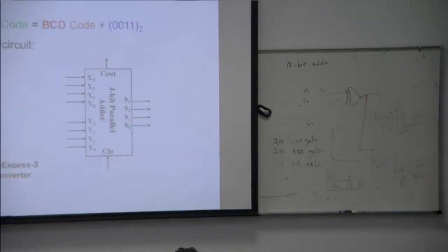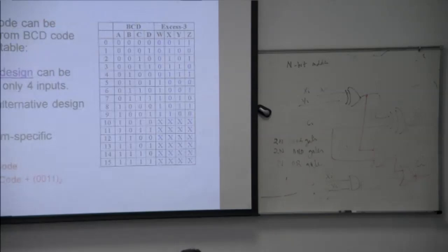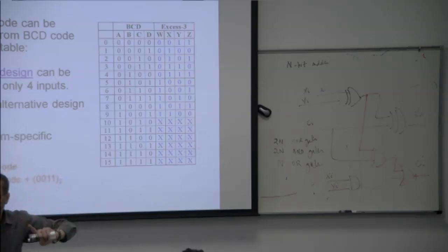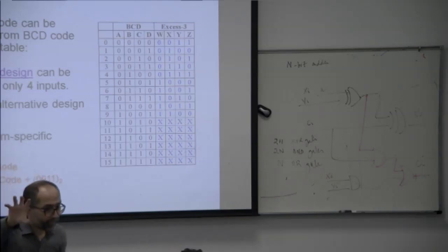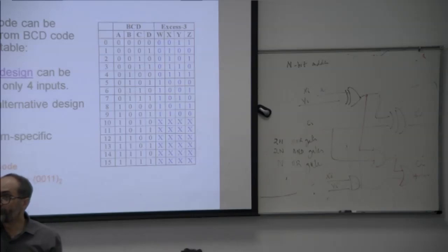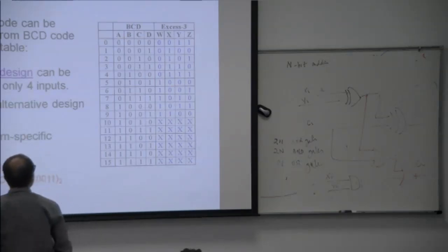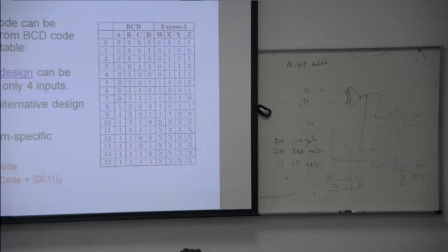Now we want to design. Okay, now we solved one problem. Remember, we solved one problem. Now we are using the block level design approach, not the gate level. We designed the BCD to XS3 code converter. Remember last time? What did we do? Draw the truth table, logic minimization. But we can also design a BCD to XS3 code converter using an adder. How? Let's see. Add 3.